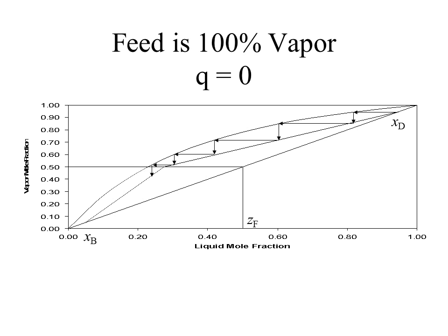Now we're going to operate off the lower operating line to finish out the distillation. We go to the equilibrium curve, lower operating line, and repeat back and forth until eventually we cross over to the composition that we want at xb. So if you count all the stages, we're feeding at the 5th, and then we have 6, 7, 8, 9 stages, so a total of 9 stages, 4 stages below the feed stage, and that would be the design of our distillation column.